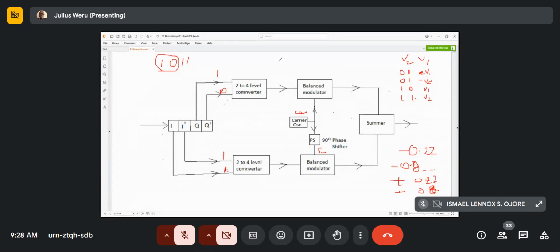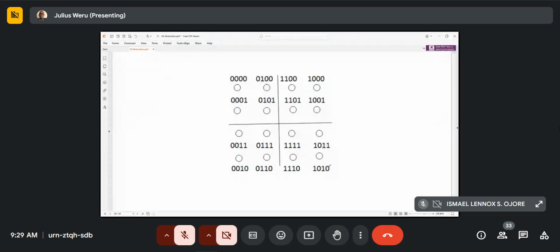The only difference with the 4 QAM or QPSK is this part. First, because you're taking 2 symbols for I and 2 symbols for Q, and then from the 2 you're generating 4 levels each, so it can be 16. That's a constellation diagram of 16.